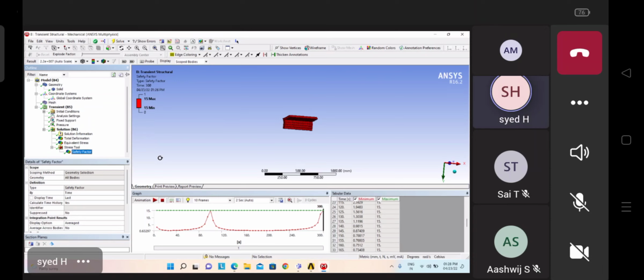Actually, what is factor of safety here? It is like actual stress by theoretical stress, something like that. So it should be under one ratio. See, theoretical value is a theoretical value, so we can't change that value here. That is the standard. For that material, that much stress it can bear. After that, it will deform completely. That is the actual property of that particular material. That we can say as the theoretical stress. Then when we are applying the load, what stress are we getting?